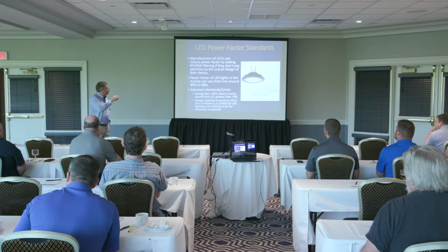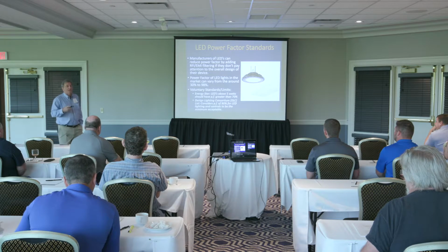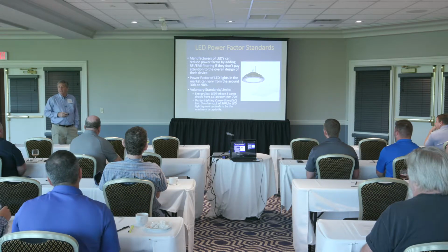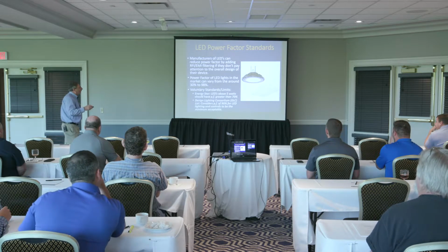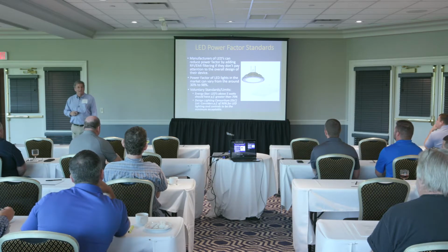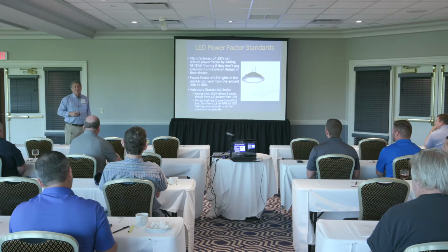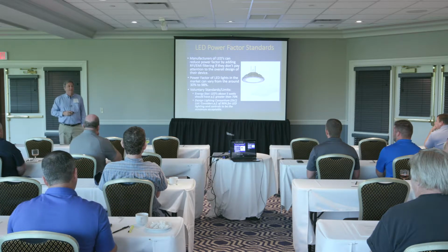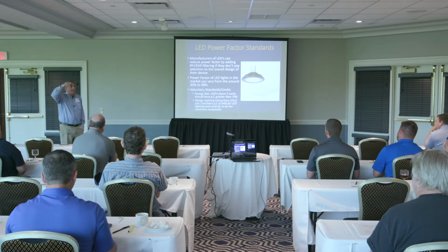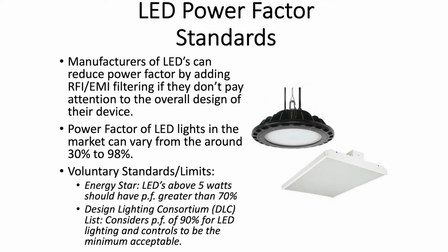If they do a good job of design, they cannot affect the power factor much at all by adding the noise reduction. Okay? So power factor of LEDs today can vary from 30% to 98%. And I'd rather be towards the top of that range than putting in a whole bunch of 30% power factor LEDs to drag my plant power factor down when I put those in. Just to give you a feel, there are 2 different standards out there that people look at.